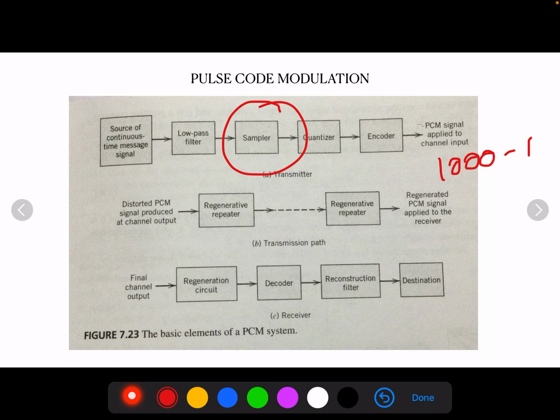In other words, the weak passages which need more protection are favored at the expense of the loud passages. In this way, a nearly uniform percentage precision is achieved throughout the greater part of the amplitude range of the input signal, with the result that fewer steps are needed than would be the case if a uniform quantizer were used.